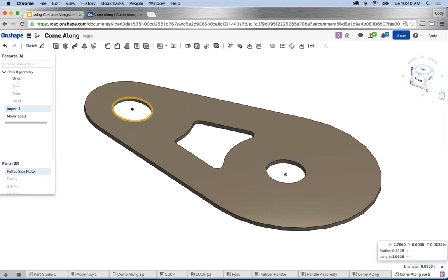If I select it, it gives me all kinds of breakdowns about the details of where it's at. But you can select anything. If I select a face, it gives me the area. If I select 2 circles, for instance, it gives me the minimum distance, but I can also see center distance and all kinds of other details. So you have integrated measure tools. It's just a matter of having highlighted geometry. Any highlighted geometry, Measure automatically comes up. Okay? And you can get more detailed if you select the flyout here.